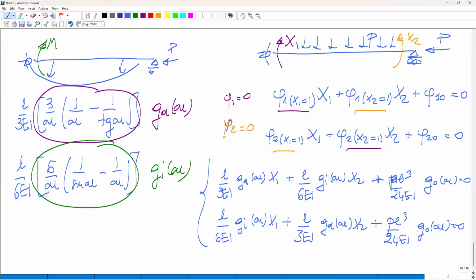The buckling failure, we said, is a situation in which you have a finite beam, finite loads, and your solution goes to infinite. With one equation, it's easy. We have a system of equations here. Let's try to elaborate the mathematical condition for buckling. This is a linear system of equations, linear because the unknowns are x1 and x2.